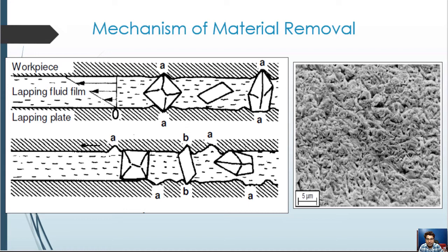Their edges, which are moving along a cycloidal path, engage the surface. Through the repeated penetration of the grains into the workpiece surface, ductile materials are sharpened until fatigue and then successively removed. In the case of hard and brittle materials, however, micro cracks are induced on the surface of the workpiece, the interconnections of which lead to the breaking away of the particles.